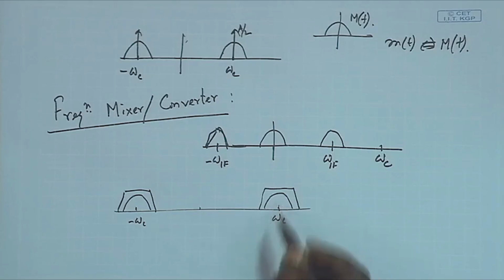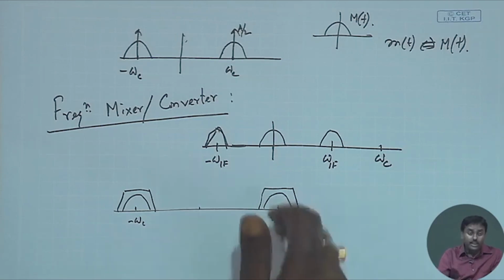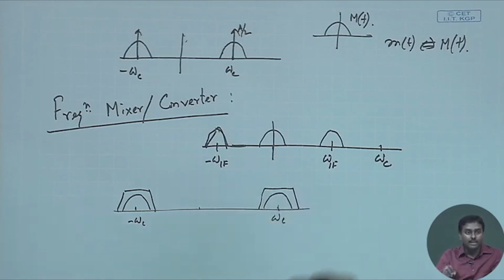Now, once I get this signal, I might have to amplify this signal. Okay, so, the received signal has to be amplified, but at that high frequency, if I wish to put amplifier circuit at high frequency, any circuit design will be very difficult, because they will all start radiating things. Okay, so, any circuit component you start putting, they will be all radiating. So, I cannot really employ any signal processing at that high frequency.